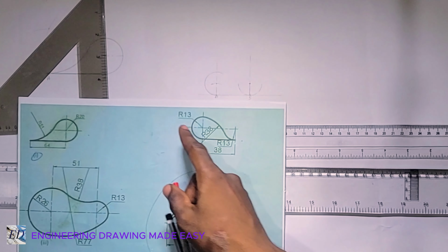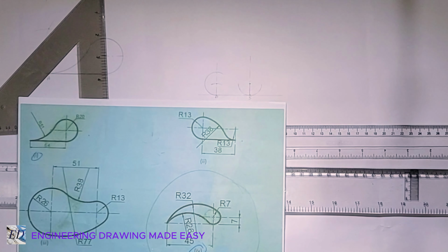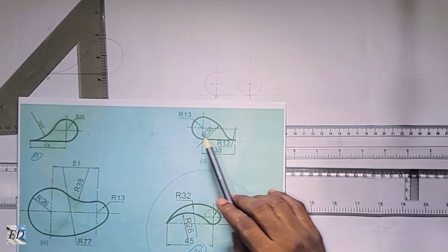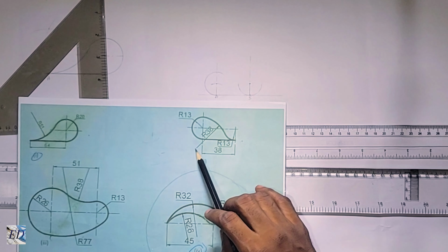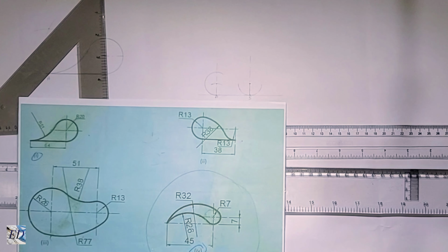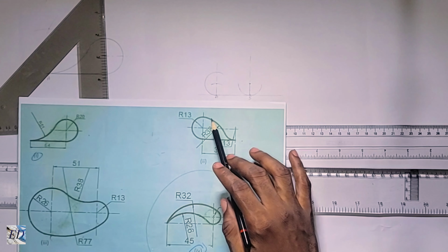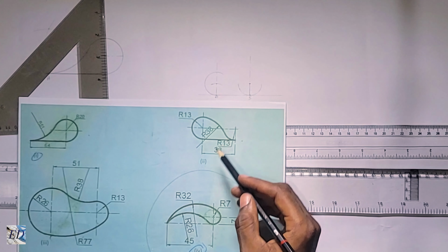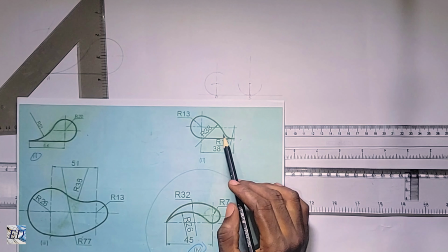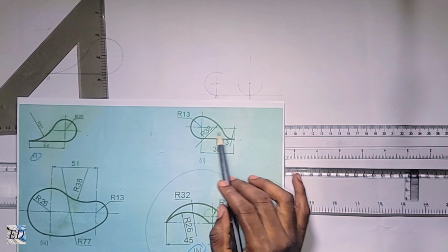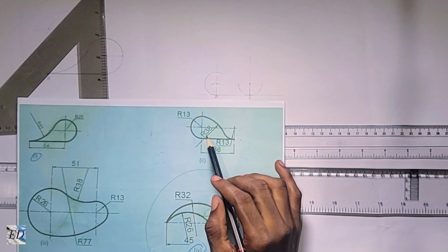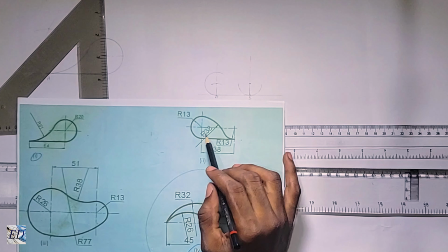Now moving on to the last component of this whole arc. This is where a new approach comes in, that you have to use your understanding from the principles of tangency. If you take a look carefully, this arc with radius 38 millimeters touches this arc externally and touches this arc internally. So the center would be the sum of these two radii and then the subtraction of this from this.